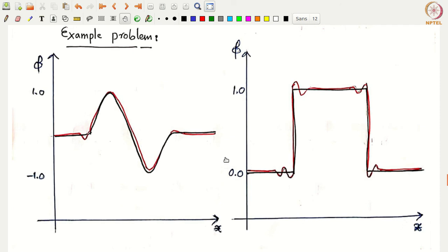As a result, there are several other methods proposed which try to fix these oscillations as well. Some of them are in the class where we construct higher order schemes for upwind differencing, because upwind difference schemes do not produce these oscillations. As a result, the upwind difference schemes are somewhat preferred because you don't get new maxima and minima. Rather, the decrease in amplitude can be fixed by going to higher order.